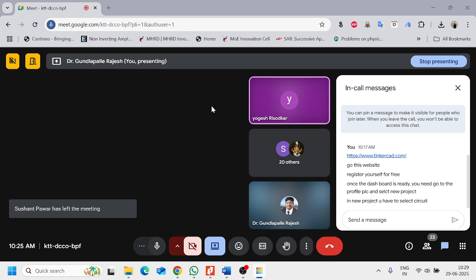Here your LED positive is connected to the 12th pin. You have pins from 0 to 13, that is 14 digital input and output pins. I have chosen the 12th pin, so we have to initialize the 12th pin: int LED equal to 12. Now wherever you have the LED built-in, it has to be replaced with LED, whatever the variable you are going to take.